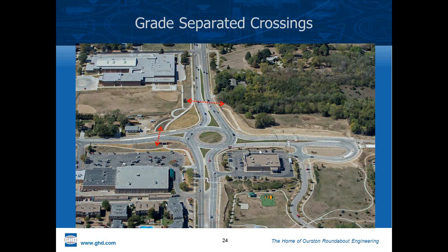This site is over in Lincoln, Nebraska. It's actually had a bit of retrofit treatment because of some of the vehicular crash problems with 3-lane entries and a lack of education to the community. But the point of the slide is to show that it has 2 underpass crossings, a middle school in this quadrant, and then 2 split crosswalk hybrid activated walk signals, one on this leg and one displaced on this leg. So it's a fully accessible intersection by U.S. Access Board standards if it has countdown, push button countdown, audible pedestrian crossing accommodation and treatments.